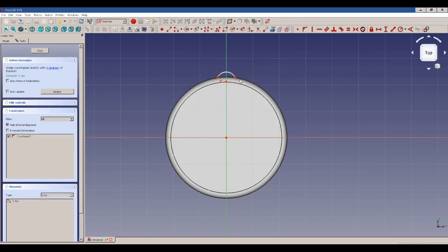One of those up there. We'll go ahead and grab the external geometry. That's this button right here, also the X button on your keyboard. Hotkeys are very valuable. We'll fix both of these points on that line. That is, where is that button? This button. Fix a point onto an object, or Shift O, which is what I'm using.